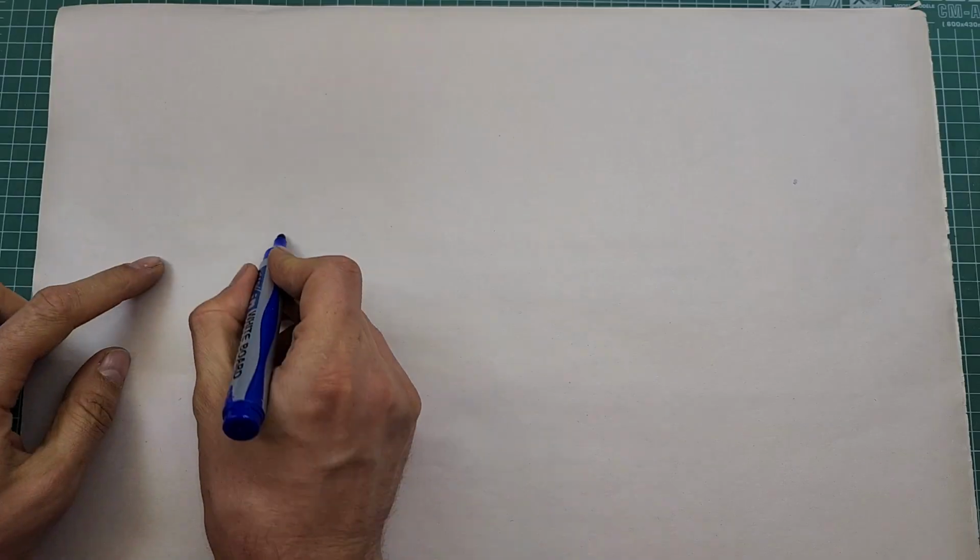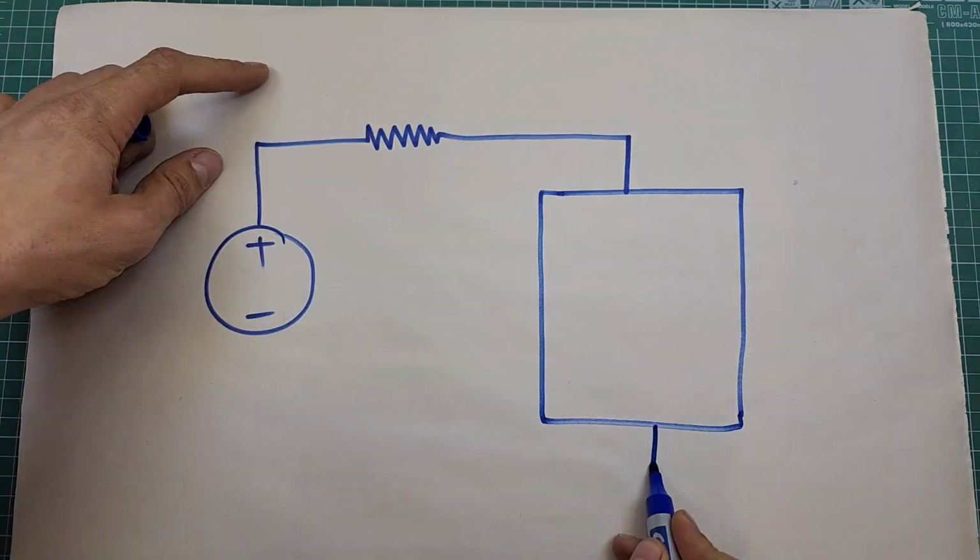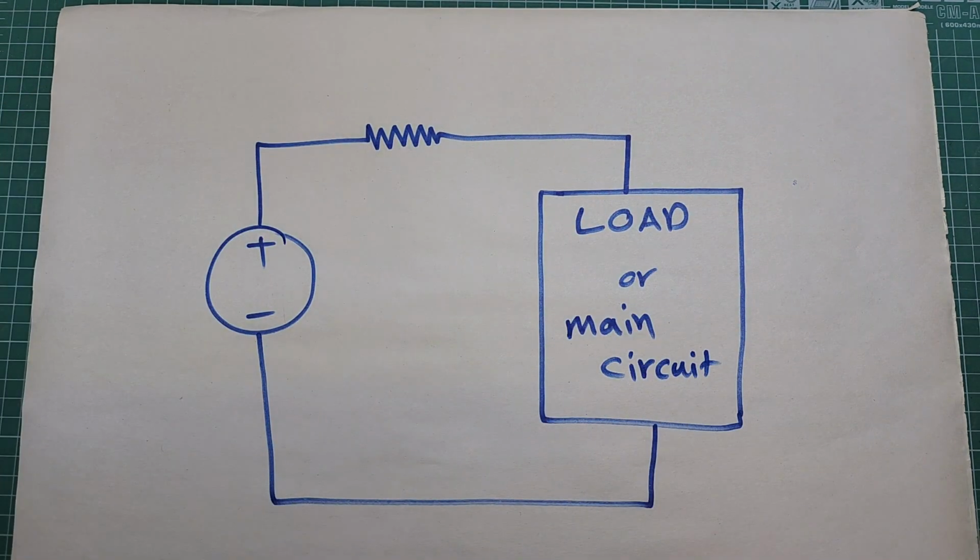Resistors that are used for current measurement are called shunt resistors and they have specific characteristics. For example, to avoid power loss or at least to have very minimal power loss, the resistance value must be very low. For instance, if you want to use a resistor of a few ohms, the power loss across the resistor will be huge. So, a resistor that is going to be used for current measurement must have a very low value, in the range of a few milliohms, for example. Having a low resistance also means that this resistor will probably be able to handle large current.